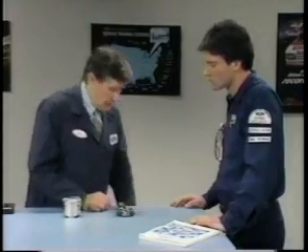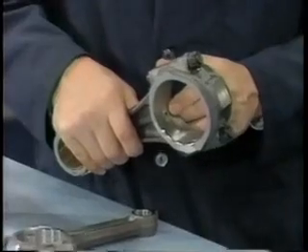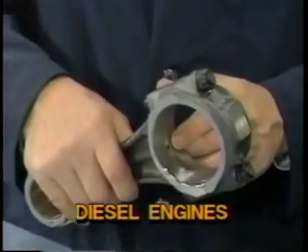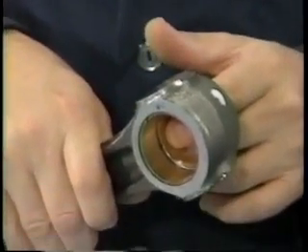Some diesel engines used by Ford lubricate the piston pin with pressurized oil rather than by a splash. In these applications, the connecting rods are rifle drilled. This rifle drilling allows oil to be routed to the connecting rod piston pin bushing from oil passages drilled in the crankshaft that feed the rod bearings. Well, I see how the major components of the engine are lubricated, either by direct oil pressure or by some method of spray or dripping.